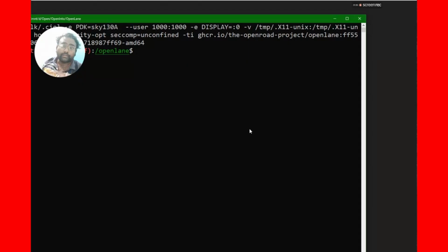The second step is to create a folder and a Verilog file to design a chip. Create a folder for the AND gate design. So we move into that. When you're doing that, the directory is designs, AND gate, and source.